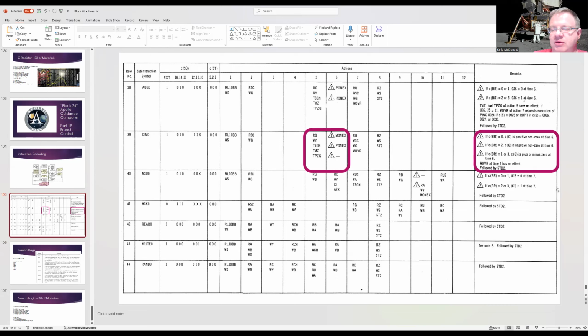So that's why we have some of that logic here, to determine when we actually want to pulse the clock for either BR1 or BR2, based on, A, do we have any of those test control pulses asserted? And then we also have a little bit of other logic because there are some cases where we just want to leave the other register alone.